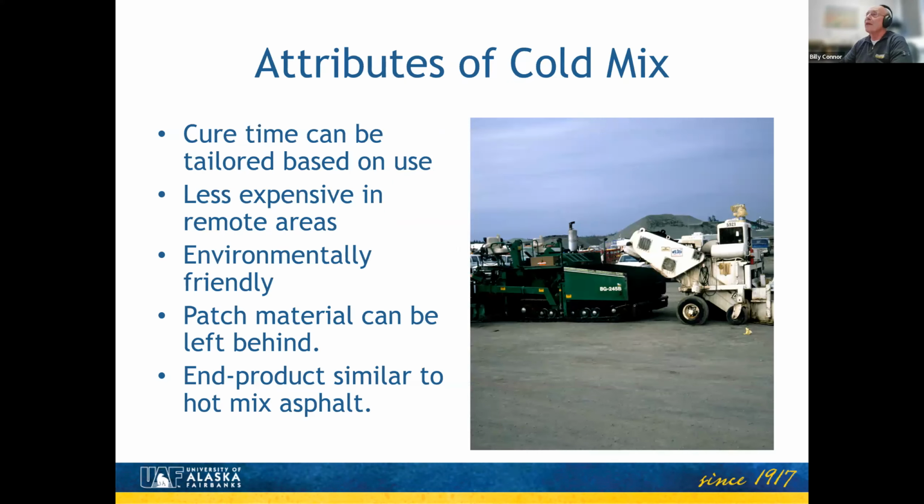Some of the attributes, cure time is tailored to be based on the use. So you need to be talking to the producer of the cold mix asphalt cement, because they can tailor it to break within minutes or hours or days. So that's something that you need to think about.